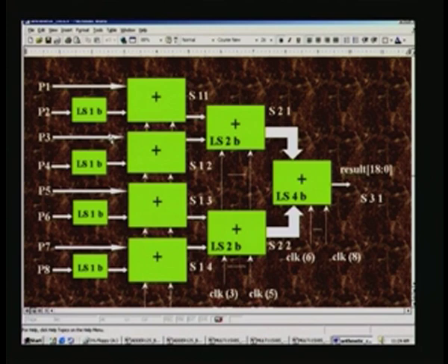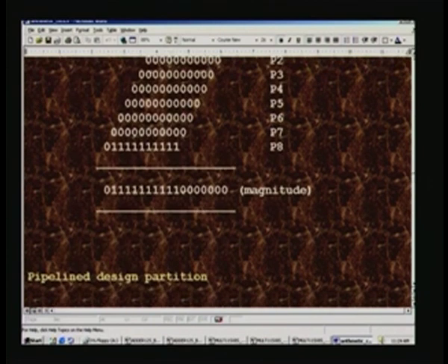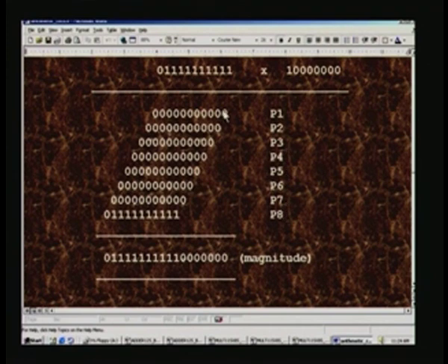And here what we do is we add, earlier we have seen the partial products are P1 through P8. What we do is we add these 2 and concurrently we add this 2, this 2, this 2 by the 4 adders of the first stage that we have seen. Out comes the result. Now while adding this one, note that we do not have to add this first bit, because there is no matching number here, it is equivalent to having a 0 there. So when you add 0 and 0 you will get 0.